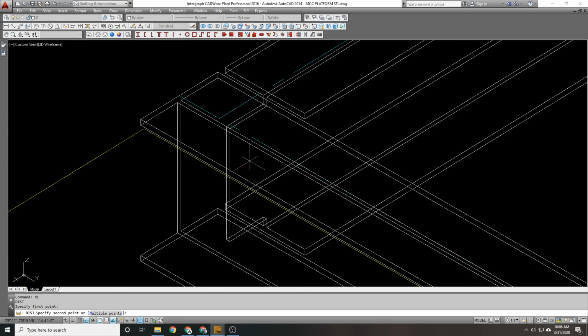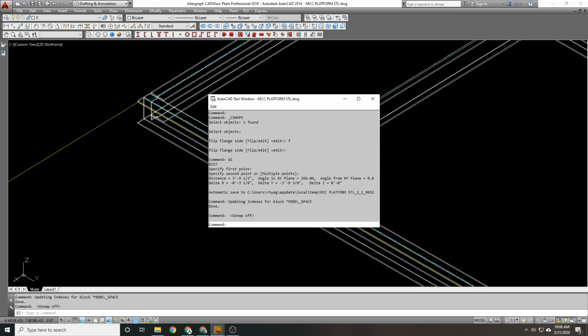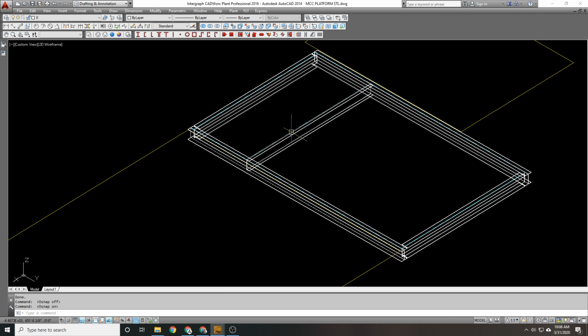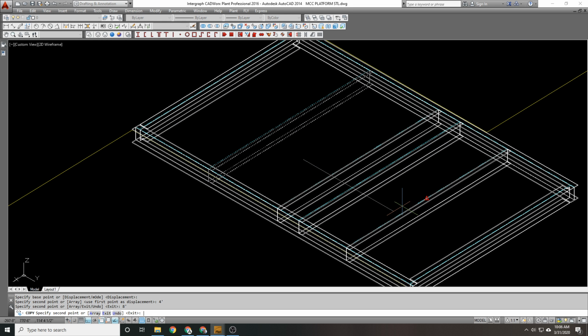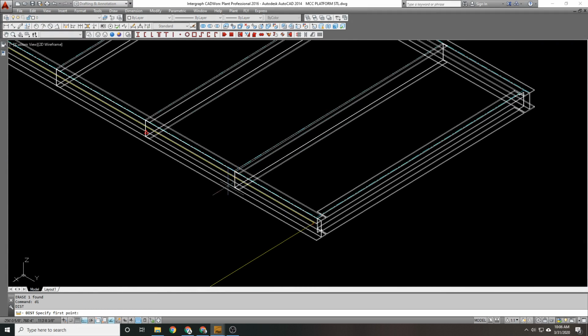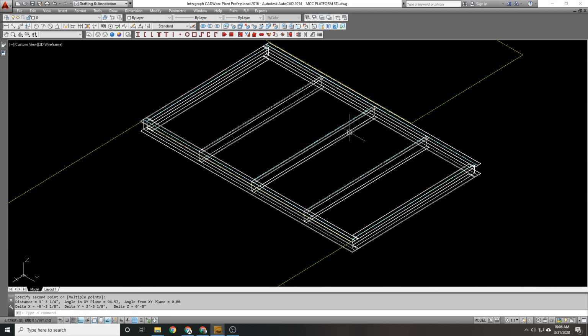And if you look at the actual span between here and here, my delta Y is 3'9", so even less than 4 feet. I'm going to stick with 4 feet, so I'm going to copy this 4 feet, 8 feet, and I think that should get me enough. I'm also going to delete the overlapping line here. And then what's the remainder is even smaller. This is 3'3". So I'm definitely okay for my grading span here.